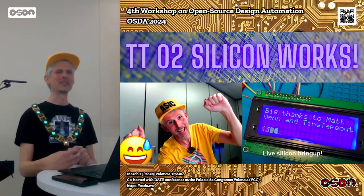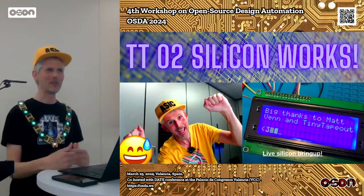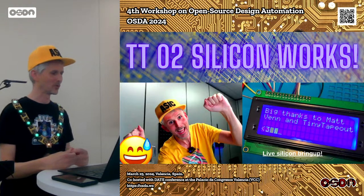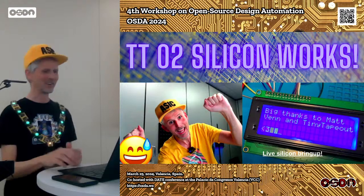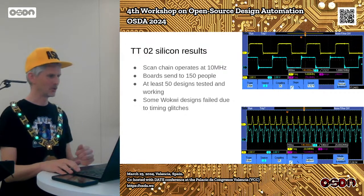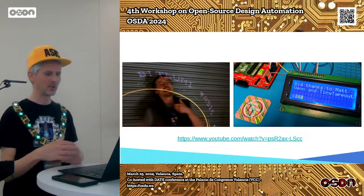We did a silicon bring up on a live stream, so that was fairly stressful, but I thought we're kind of pushing a lot of boundaries here by doing stuff with open source tools. So normally you don't get to know if a chip works first time, but we thought we would live stream it. It was pretty slow, we're running it at 10 megahertz, and it does work. We've sent it out to 150 people, and people are testing their designs.